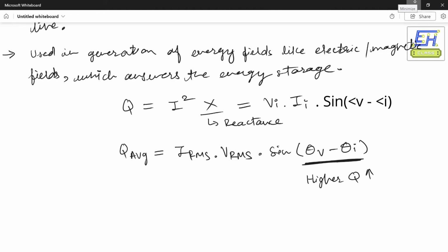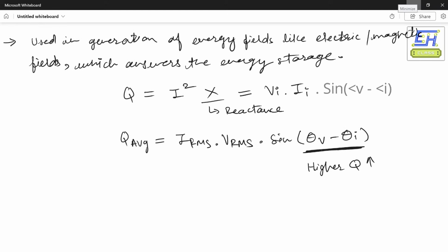And this is the same with the power factor. So if the gap is less, the better will be your power factor, closer to 1, and that is how efficiently you use the energy. So this average reactive power will be positive for an inductor and negative for a capacitor. And why is this so? Because it's essentially by the nature of this component.